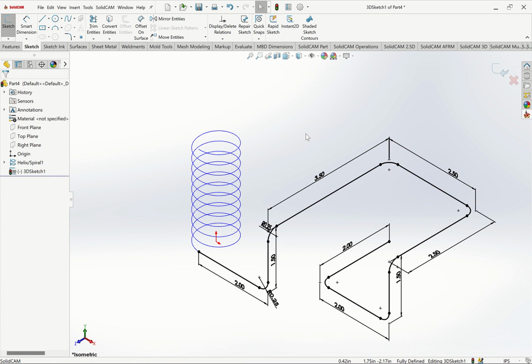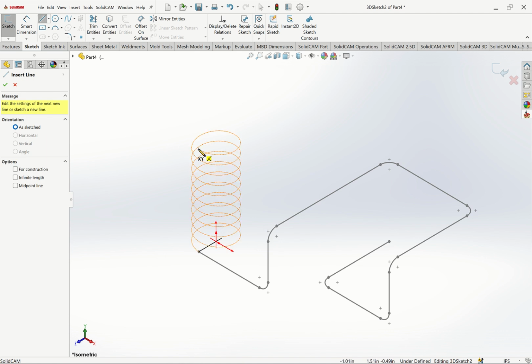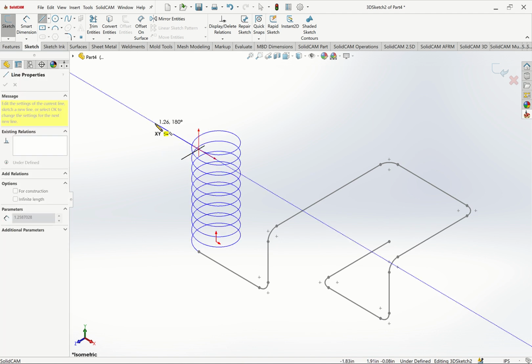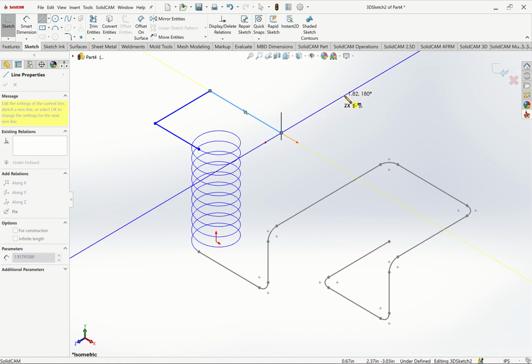Next, we want to put the second part, the second fillet. So click here, exit. Then come to 3D sketch again. We want to pick a line. From this line, pick from this far end, go this direction. Then click tab, go here, then tab, follow this path, and then the last one like here.